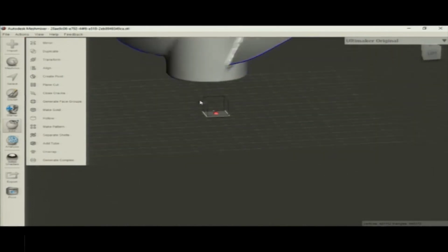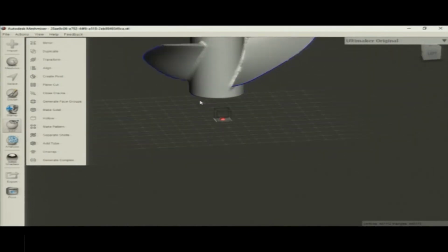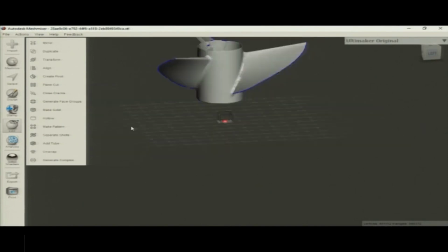See what is now happening here. This is our 3D printer envelope, the small cube at the bottom. This is the 3D printing envelope, and this is the object. The object is of the order of 2 meters or so. The 3D printing envelope is smaller. So, we have to first fit this object into the envelope. We need to scale down the model, according to our print volume.